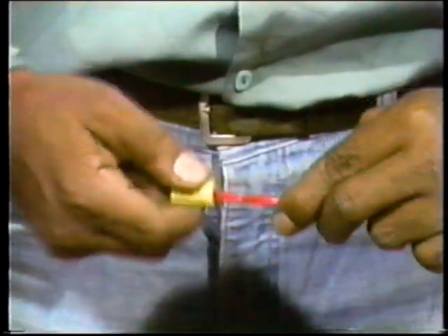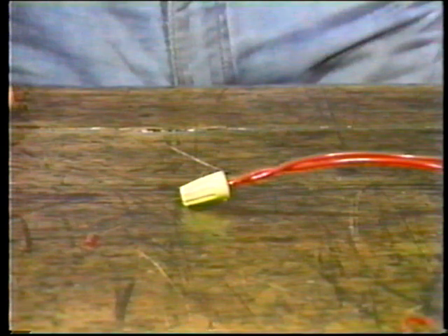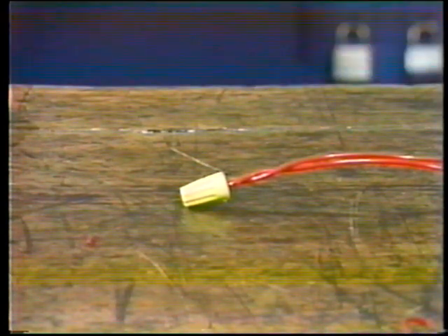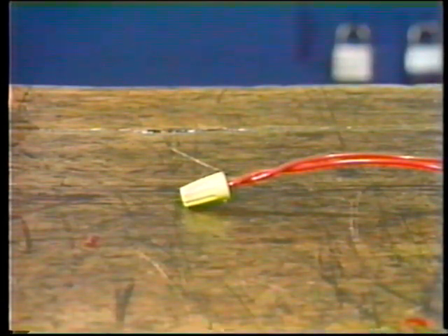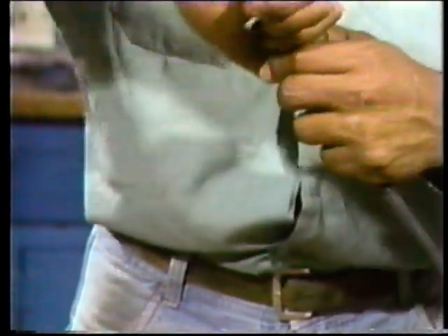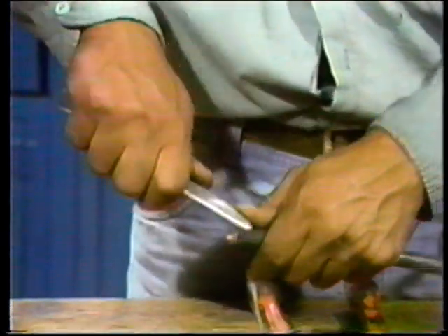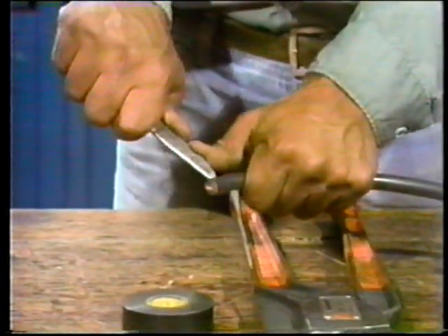The splice is complete. Now Bill's going to be working with larger conductors. He's already chosen the sleeve he's going to use based on the two factors we mentioned, size and metal. He places the barrel of the sleeve next to the end of the conductor and puts his thumb where he'll start to strip. He'll use a knife to do the job this time because the conductors are so much bigger. He makes a 360-degree cut around the insulation at the mark. He has to be careful not to nick the metal of the conductor as he works.